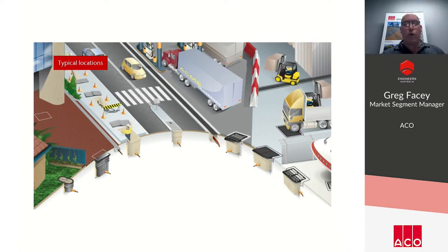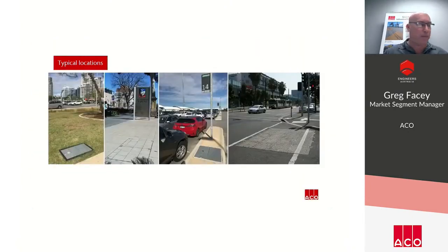So in summary, single wall plastic pits for lighter duty landscape pedestrian applications, or for vehicular traffic and or pedestrian applications, you want to be looking to use a rigid pit in the forms of those materials that we spoke about. Understanding the requirements of the location will determine the selection of the enclosure and cover. So there is a reasonable degree of collaboration with all the stakeholders which may be required, particularly in high aesthetic applications, just to ensure not only the functionality of the enclosure is met, but also the aesthetic form is achieved to meet the visual requirements of the project.